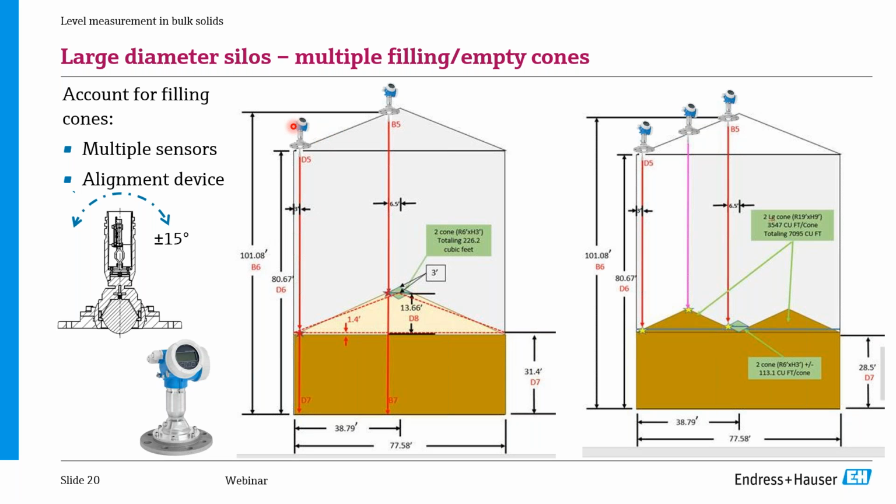So you can send all this information to your PLC or to your control system, and do the math and the calculations to see what the average level is. And if you have very large silos with several filling nozzles, you can even use more than 2 devices, or 3. There are even cases where you can have up to 8 measurements to really understand the product surface profile.